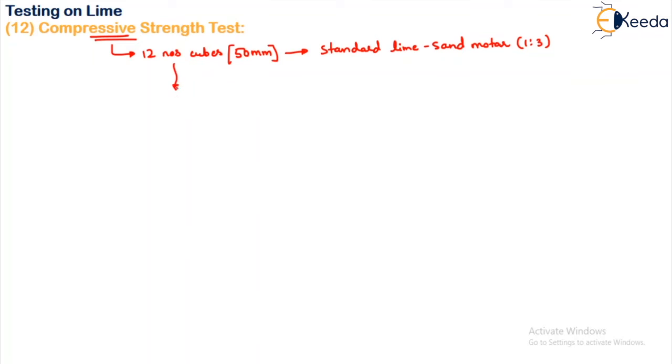Now we have to keep these cubes undisturbed for about 72 hours at atmosphere. Whatever the atmospheric temperature is, we keep it in that.